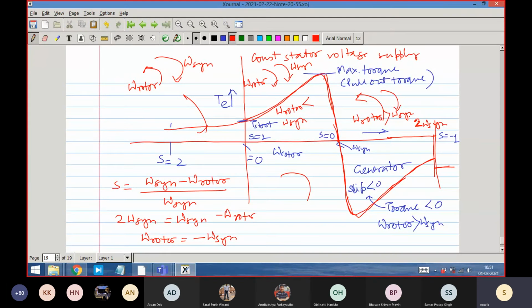That is possible when there is a prime mover. Now the energy will be coming from the mechanical side to the electrical side. The mechanical side pushes the power, and the electrical side acts like a generator, pushing it to some electrical load. The power given to the electrical load is electrical in nature, because the prime mover, such as a turbine, gives the power and rotates the rotor.